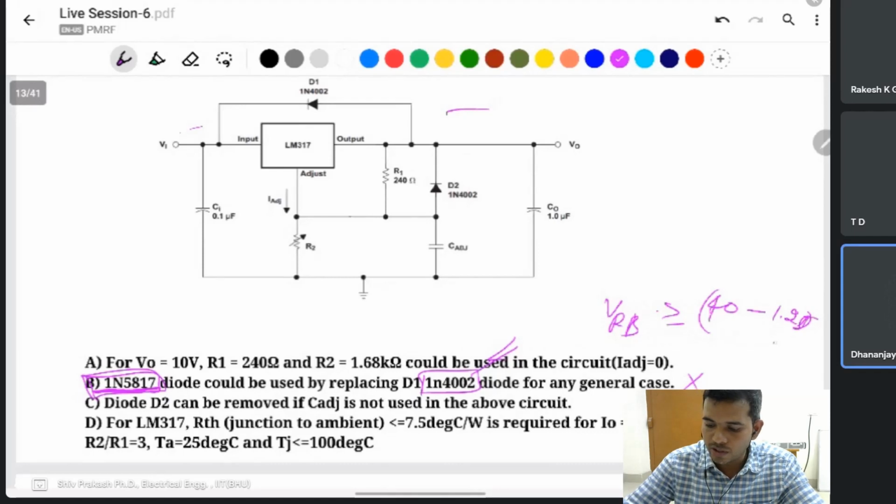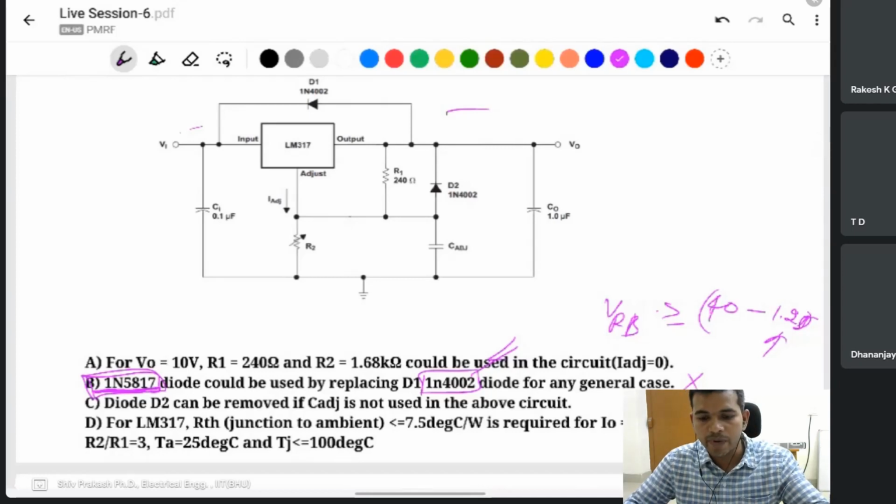Yes. For Schottky, the forward voltage is less, but the blocking voltage is also less. Forward voltage is very low for a Schottky diode. In all SMPS, switch mode power supply, where you learn about the DC-DC converter, only Schottky diode is used. A normal diode can't be used in that case, because the resistance and forward voltage are both less compared to a general purpose diode.